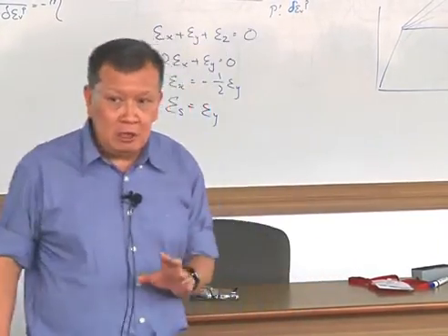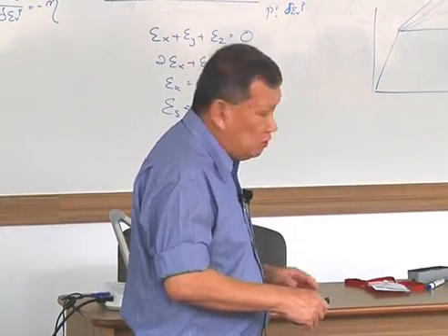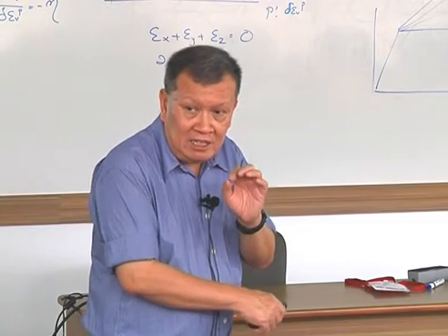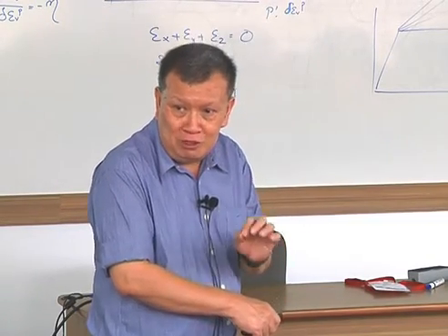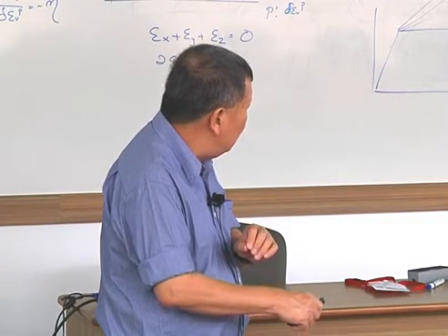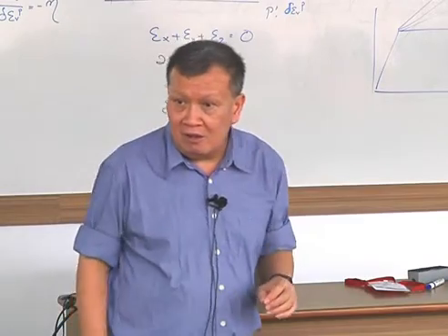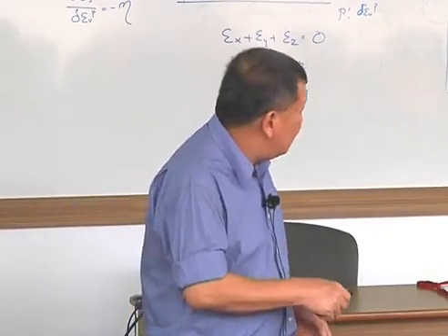Okay? So essentially, you can use this point as the U point. There's no harm. There's no hard and fast rule to say how you should choose the U point. But if you use this as a U point, then you have to use this secant modulus from here to here. And then, obviously, you cannot use much of an angle of dilation.